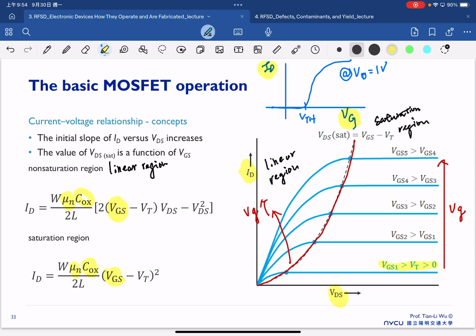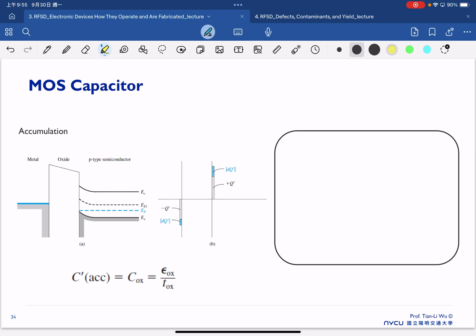So the next question we need to understand is the basic characteristic of the oxide capacitance, especially related to the different bias and different frequency. So that's why in every semiconductor class, there's always one chapter talking about the MOS capacitance. So when we talk about MOS capacitance, first we need to understand how we usually characterize our capacitance. So usually when we try to characterize our capacitance characteristic, we consider a bias. So this is our gate bias.